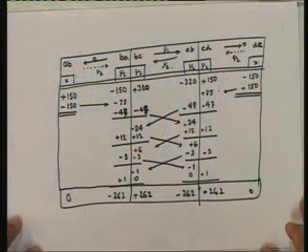So if I want to review what I have done today, I have looked at the moment distribution method as applied to beams. We have looked at how modified members can be incorporated into the moment distribution. Okay. We have seen the physical understanding behind the moment distribution method, and then we have applied it in a distribution phase, carryover phase, distribution phase, carryover phase. Okay. We saw how to consider support settlements into the entire consideration.